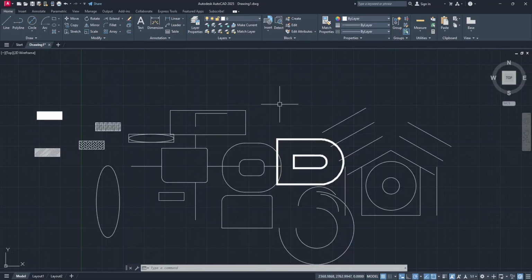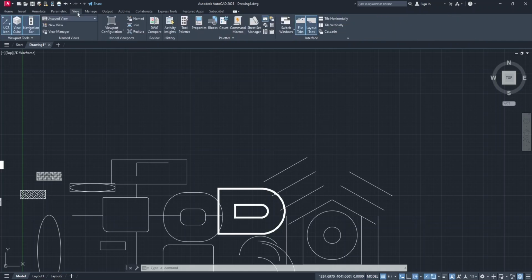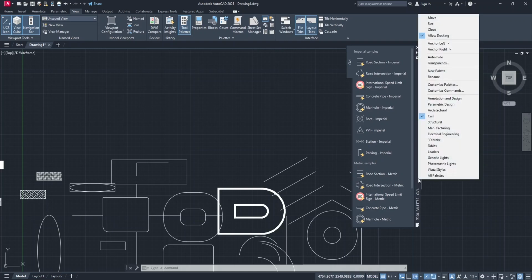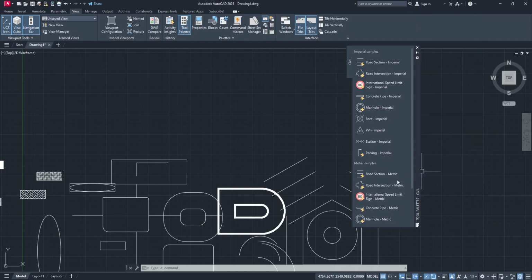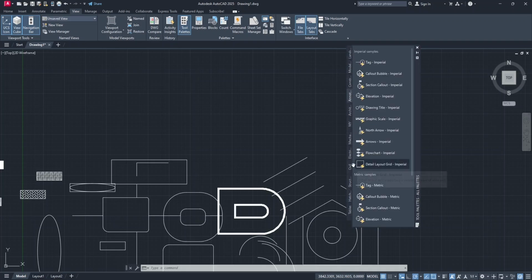Now what you do with this is to help you organize your drawing. Now I will pan a little, and there are symbols in AutoCAD hidden which are meant to help you. You can find them on the View tab. On the Palettes panel, there is Tool Palette. If you click it, you will get this small palette. If you come here and right click, select all palettes, you can see all of them. You can go ahead and explore them, but let me show you what they do.